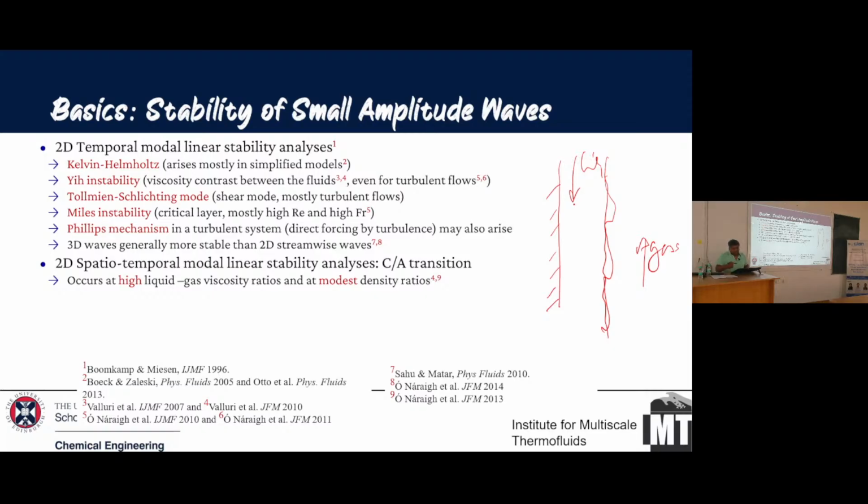If you keep increasing your gas flow rate, at some point, while the liquid is going down and the gas is flowing up, some of these waves become a standing wave. It's just a balance between surface tension, inertia and gravity. This point is called the loading condition.